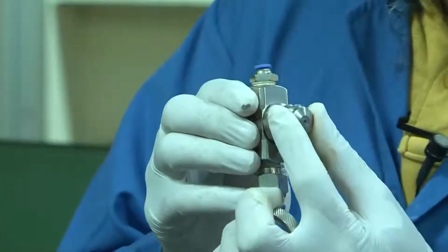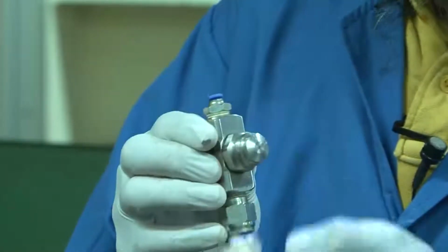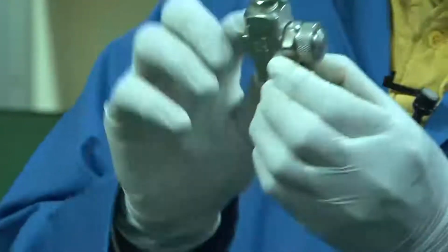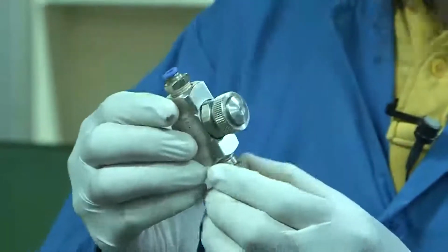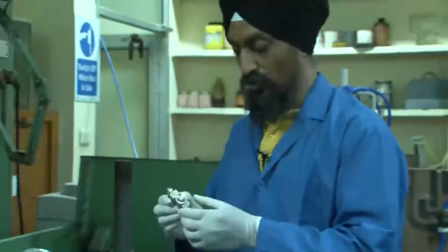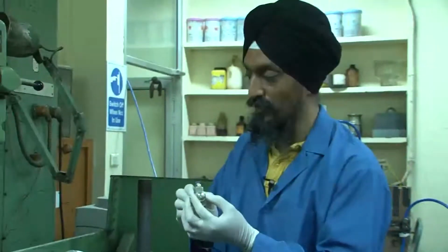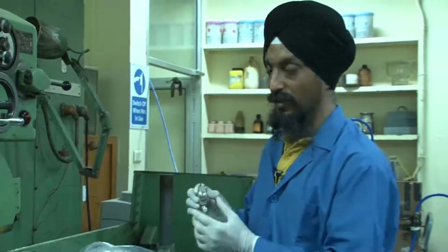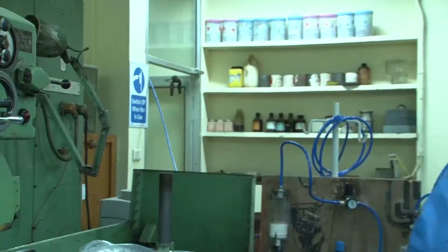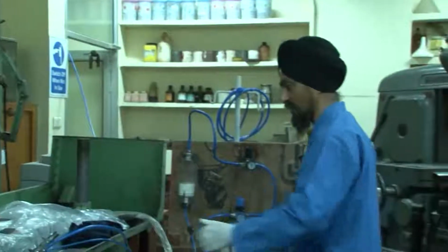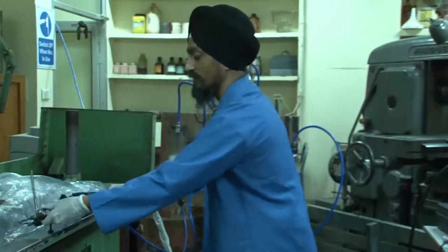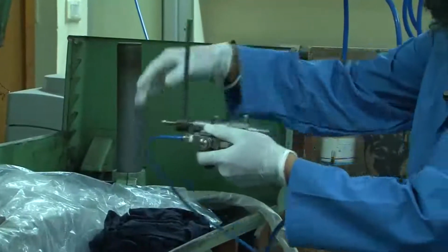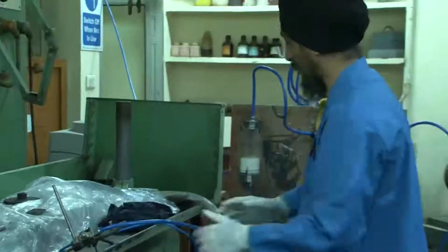In this case, I put this air cap here and lock it with my screw. I have a lock nut here, and the other body parts are already discussed, and it is already fixed here. This has been calibrated so that we get streamlined flow, so that machining is done in a good way. We have these pressure gauges, and this is the line which is giving air. And in this case we have liquid, and we have used a separate setup here.